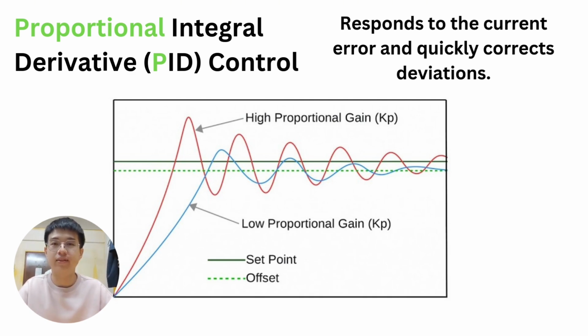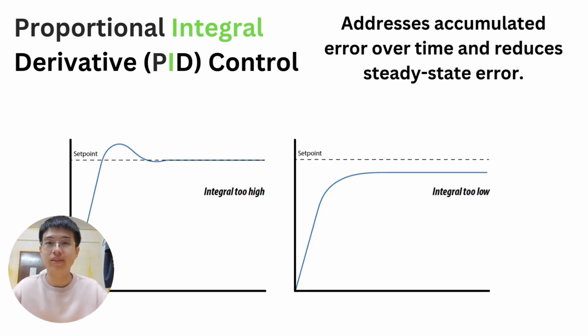For example, if the circuit's output is too high or low, the proportional controller adjusts the input proportionally to reduce the difference. Next, the integral term is responsible for speeding up the process towards acquiring desired values and eliminating the errors due to the proportional term. However, as the integral term accumulates the sum of past values to reduce the error, it could cause the system to overshoot from the desired values.